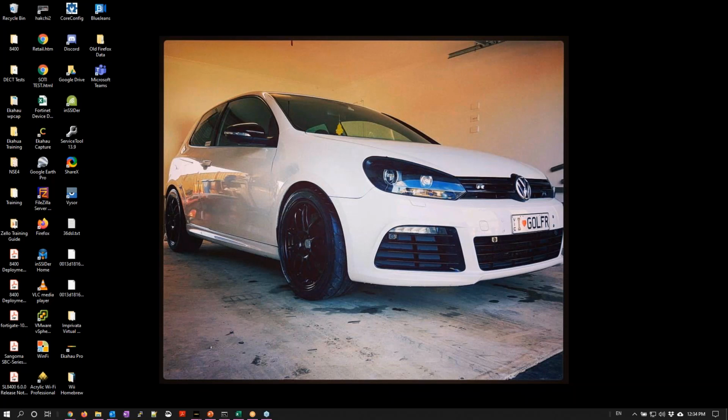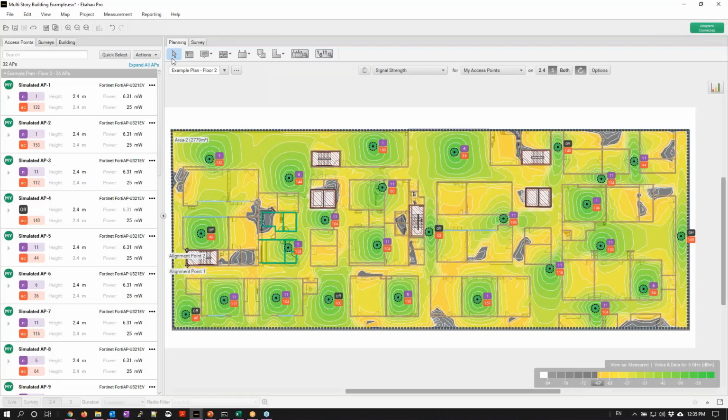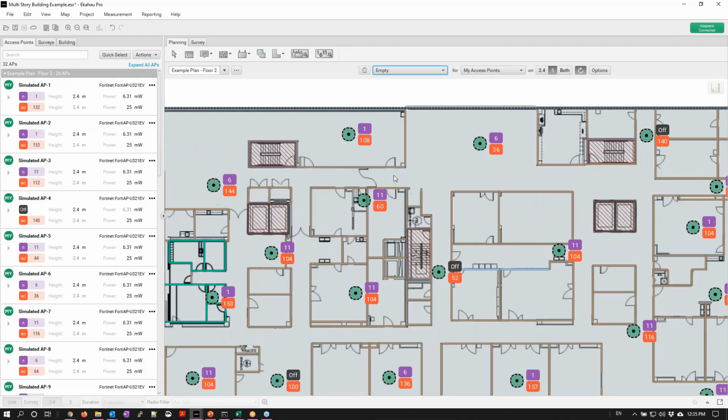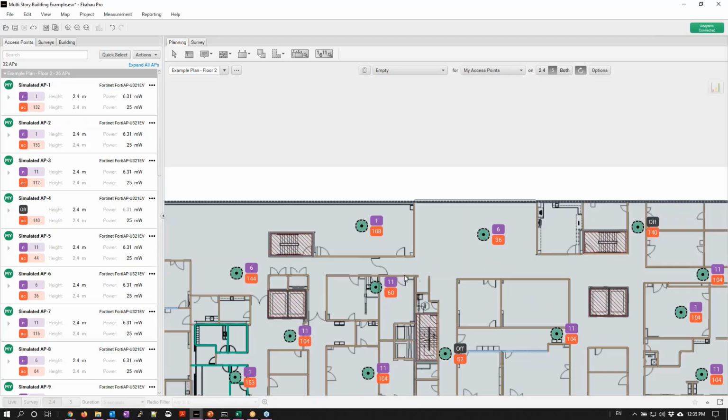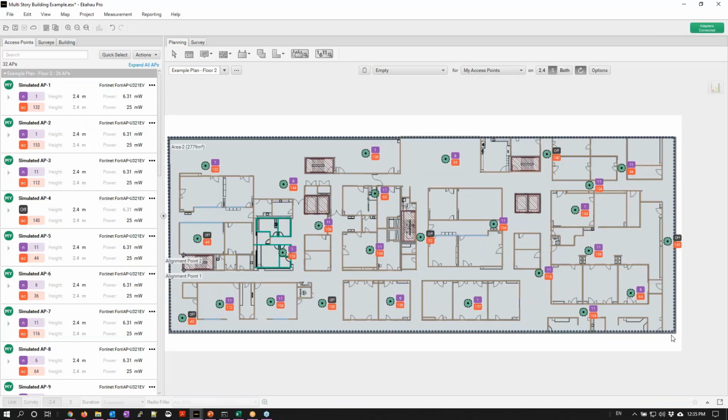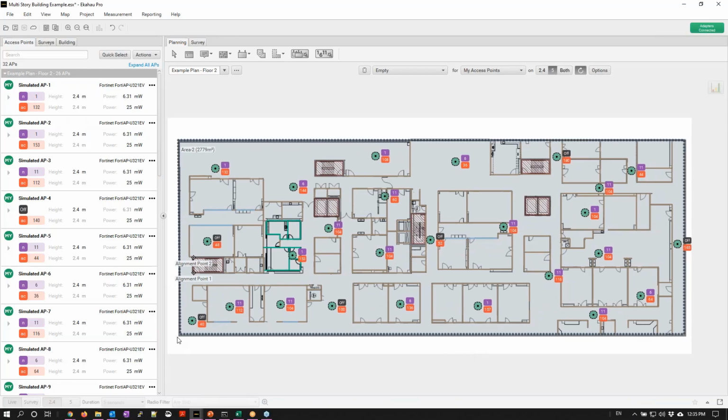So in terms of scale, if you're at a complete loss, then generally I try and look for a doorway that looks as close. And again, this isn't the greatest example, but look for a door that looks like a standard doorway and measure it to 1 meter. If you've got a full scale length of the building, so you can find the building on Google Maps is a great example, and then get the measurement from end to end. Measuring it at that distance will give you a far more accurate indication of the actual full size site itself.